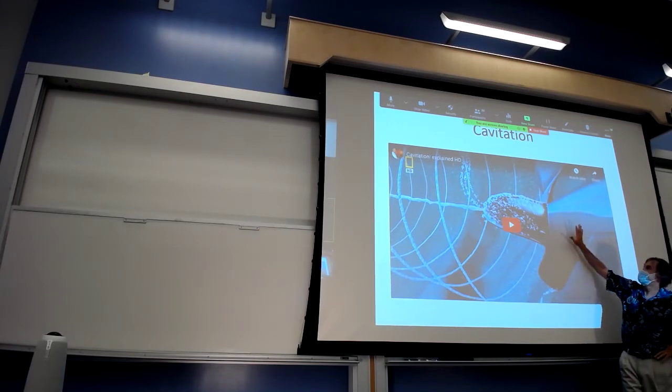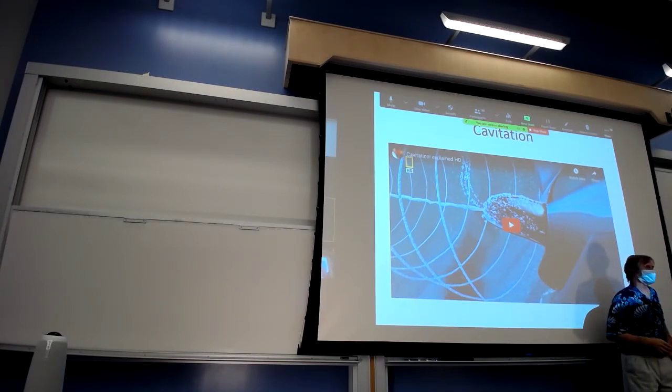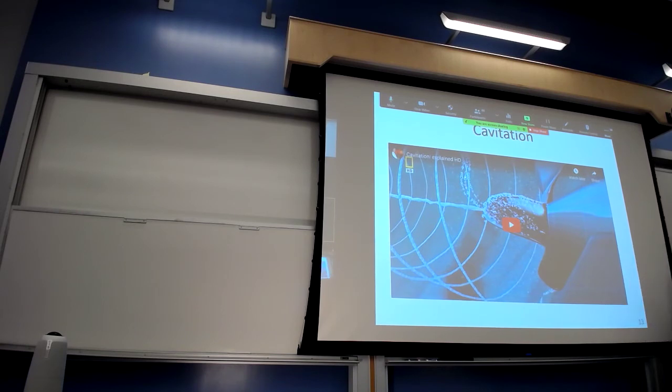So I'll let you listen to the video. But again, think of any underwater movie you've seen, and you see these bubbles around propellers or torpedoes, and everything's submerged. So where do those bubbles come from? What happens is, around the edge of this propeller, you've decreased the pressure to below vapor pressure. And so at ambient temperatures, that fluid's boiling, and the bubbles are what you see.